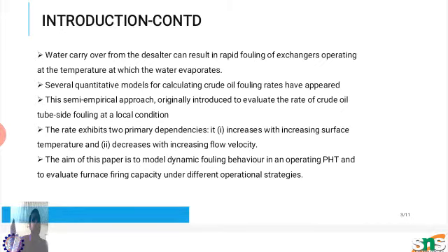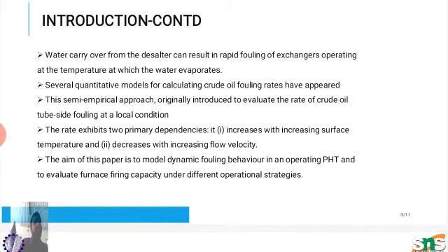Control of the throughput is achieved through partial opening and closing of the control valves and bypass streams. PHTs can experience hydraulic limitations in two ways. Fouling causes an increase in resistance to flow. If the flow resistance increases to the extent that the centrifugal pump is unable to deliver the required throughput, a reduction in throughput will occur with the buildup of foulant.